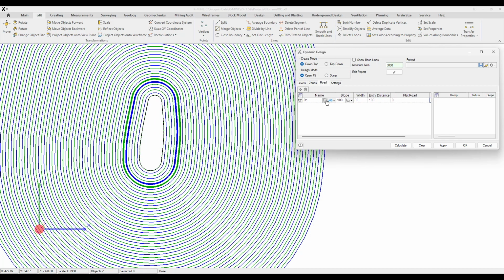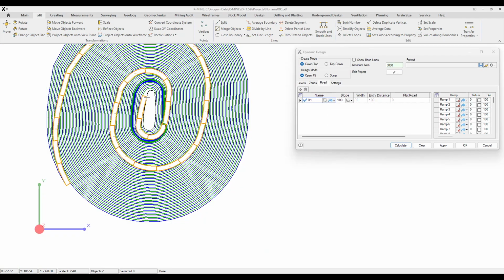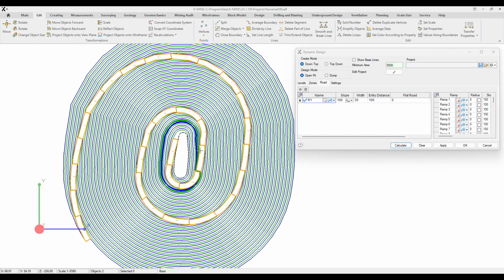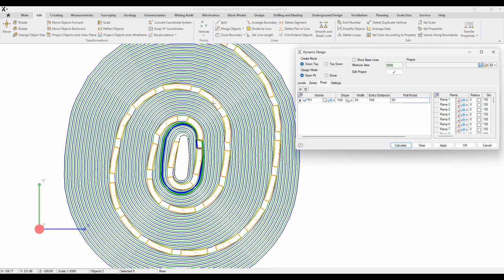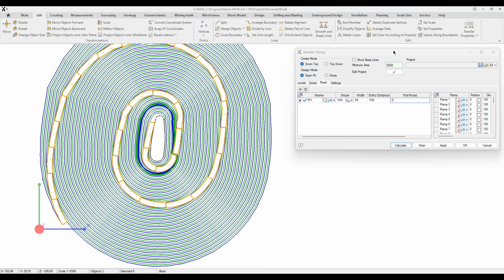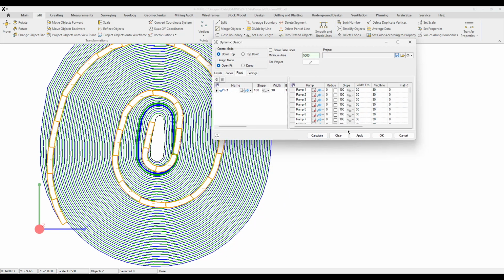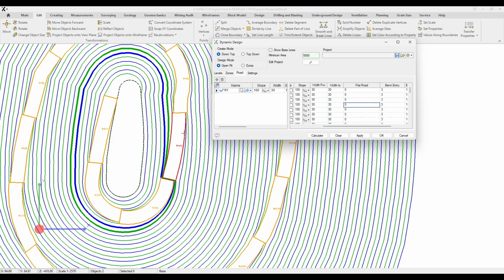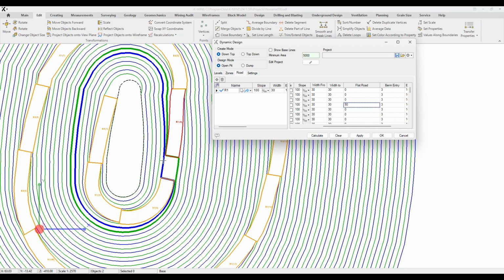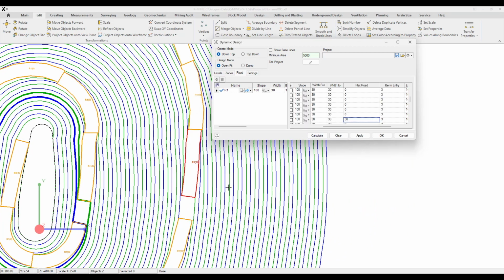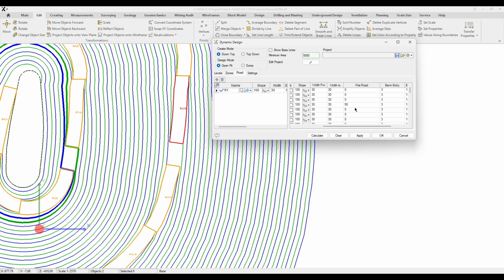Now come the roads. There are no pits without roads. To provide access from the pit bottom to the ground surface, we select the starting point of a road at the pit bottom, enter the road parameters, and then click Calculate. What's intriguing is that we can immediately see where the road comes to the surface, interfere promptly if there's a problem with the design, relocate the starting point of the road, add horizontal inserts or switchbacks, expand switchbacks, add more roads, change ramp width, terminate a ramp, and so on.